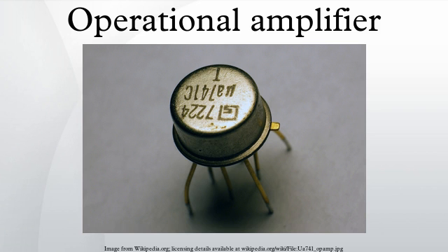of about 6. Frequency compensation: the innovation of the Fairchild μA741 was the introduction of frequency compensation via an on-chip capacitor, simplifying application of the op-amp by eliminating the need for external components for this function. The 30 pF capacitor stabilizes the amplifier via Miller compensation and functions in a manner similar to an op-amp integrator circuit. Also known as dominant pole compensation because it introduces a pole that masks the effects of other poles into the open-loop frequency response. In a 741 op-amp this pole can be as low as 10 Hz.